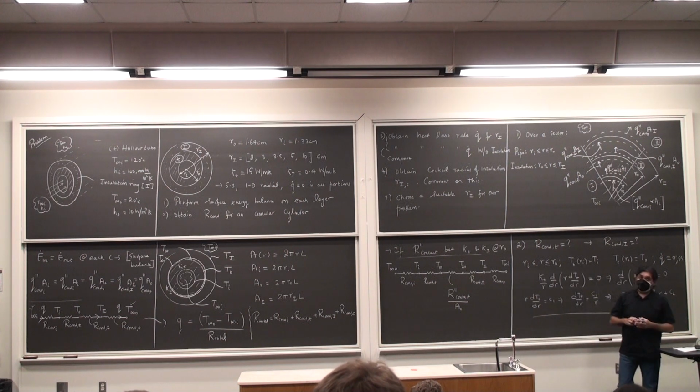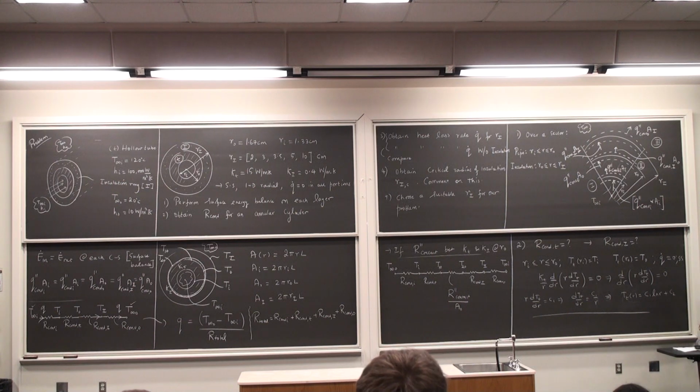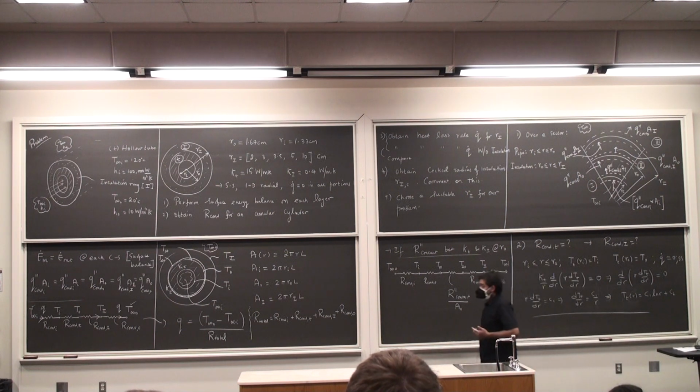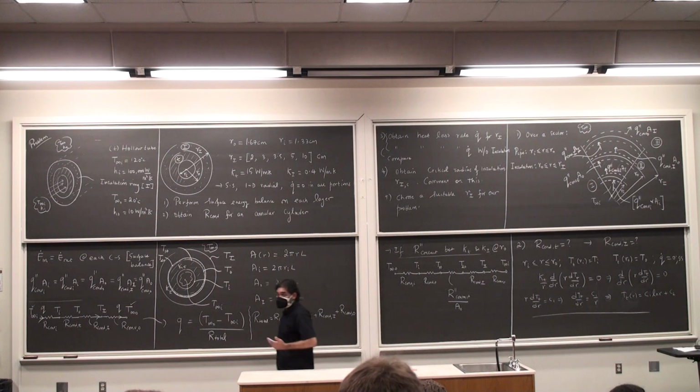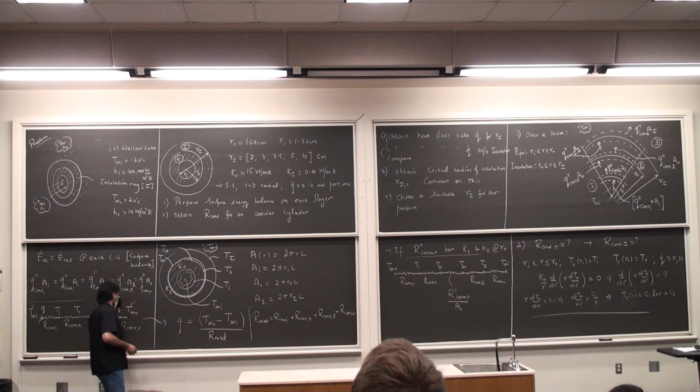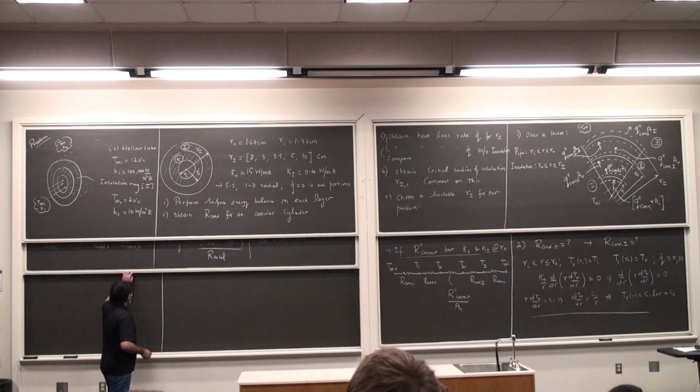But if I have a hollow body, a hollow cylindrical shell or a hollow spherical shell, I cannot get rid of this particular term, because my radius range is not starting from 0. It's starting from Ri to R0. So I will have a finite value for my temperature and also for logarithm R at the Ri and the R0 values. So please be careful. I cannot get rid of the log R term.